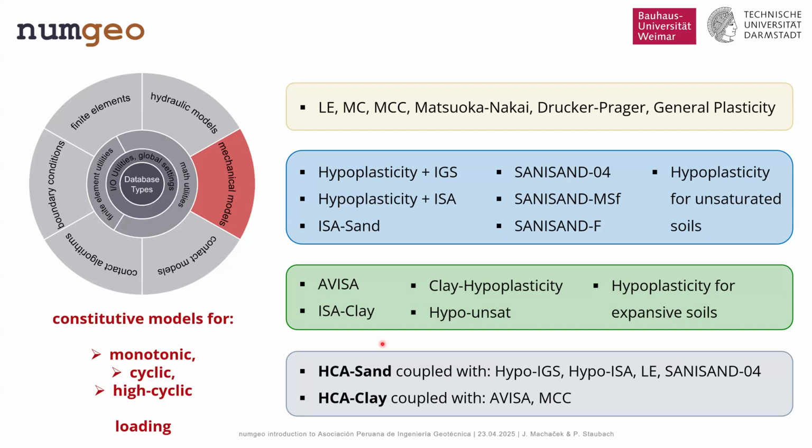So this is quite a different type of cyclic loading compared to what we're usually looking at, for example, in the context of earthquake engineering. And for these types of models, we have special high cycle accumulation models. We have one for sand and one for clay. These models take care of the behavior under this high cyclic loading. We need to couple them with conventional constitutive models that are better suited for the monotonic and low cyclic phase or loading cases. And we couple them with the hypoplastic models and also with sand models.